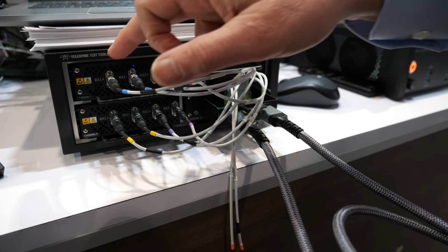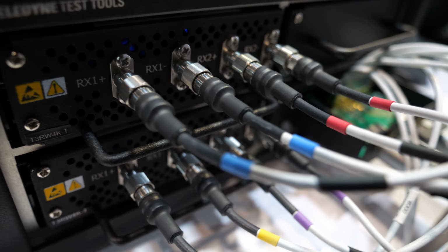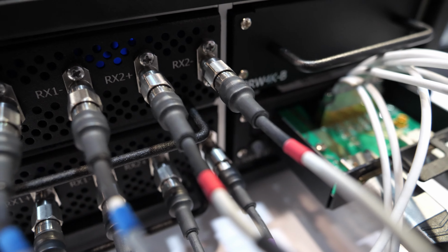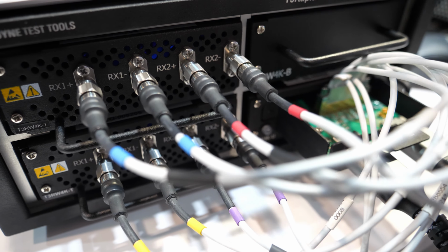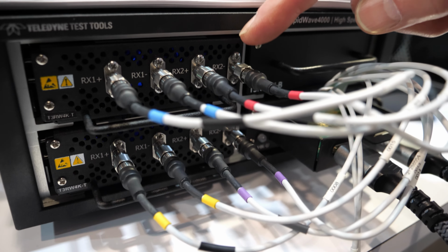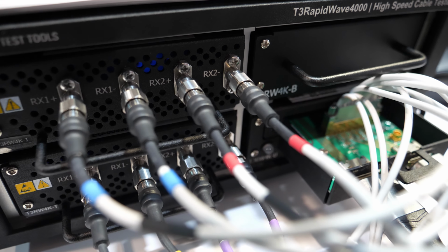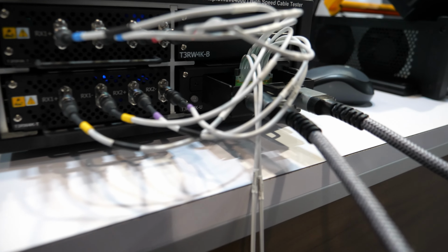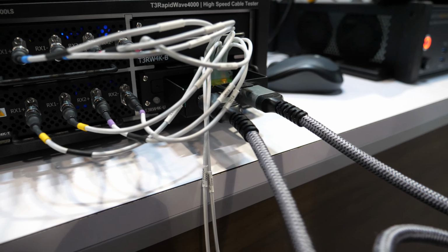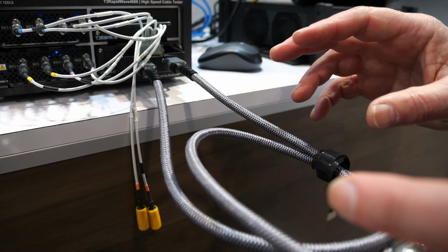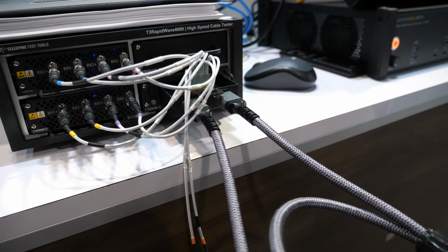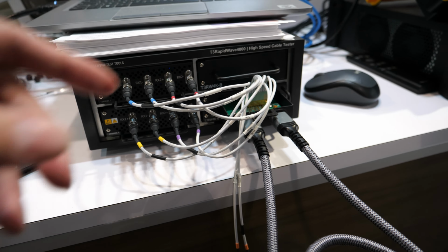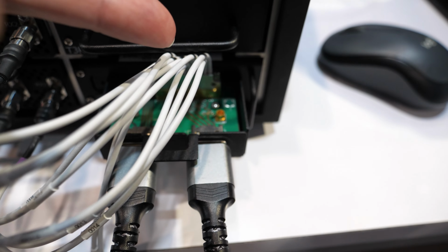These are just 2 modules that are each testing 2 different differential pairs. Here you have a digital oscilloscope up to 35 gigahertz bandwidth, and you can measure, as I said, the eye diagram and the insertion loss. Here you have also the TDR, time domain reflectometry, so the capability to test along the cable the characteristic impedance profile, which is fundamental in order to see the geometry of the cable. If you have any mechanical variation, this is detected immediately, and this gives you the idea that there is an imperfection of the cable.